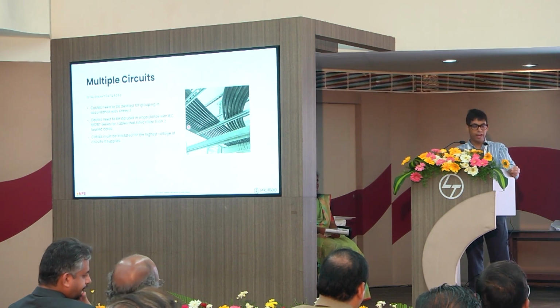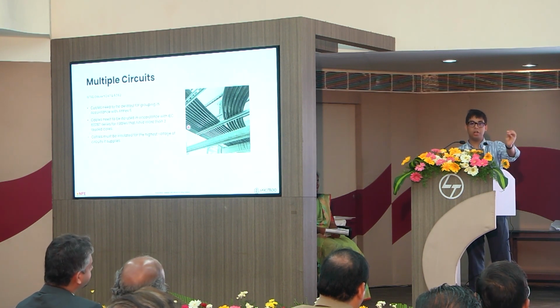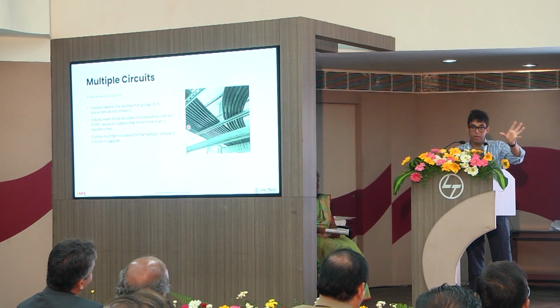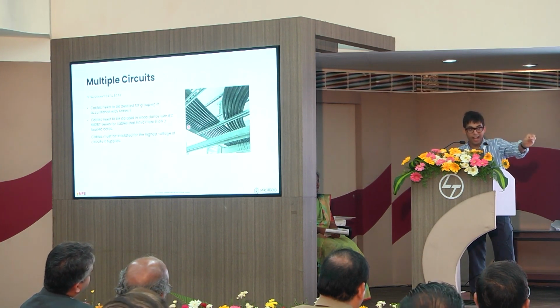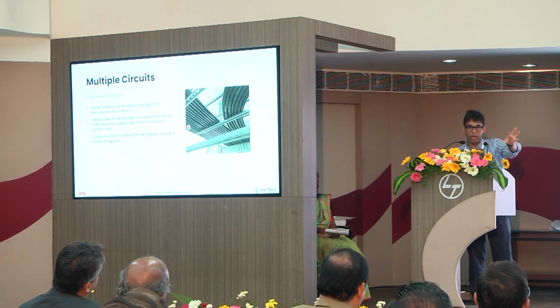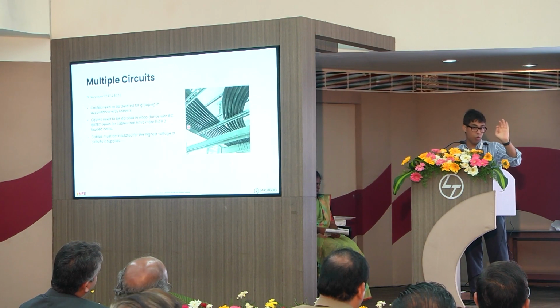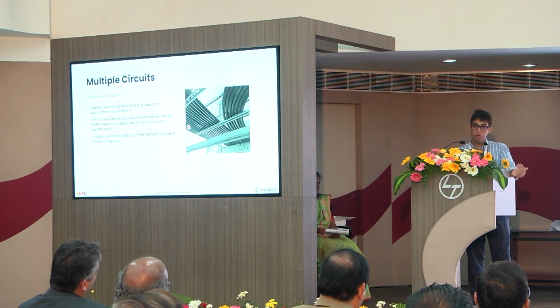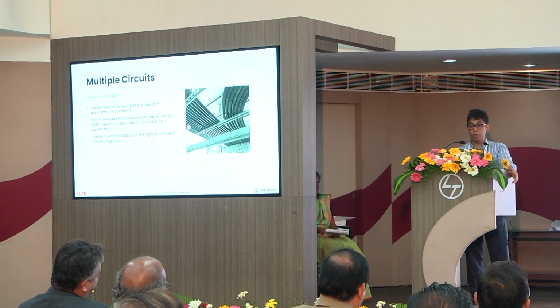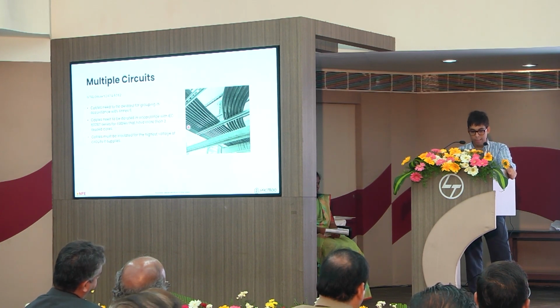But if you're going to do that, you need to realize that then 5 conductors are going to have current flowing through them. And as per Annex S and IS 694, IS 7098, all these standards give current carrying capacity for 3 loaded conductors for 3-phase, because they are assuming the neutral will carry no current, and 2 loaded conductors for single-phase cable. So again, you have to derate. In the case of 5 conductors, the factor is 0.72. So only 72% of the current carrying capacity can be utilized.